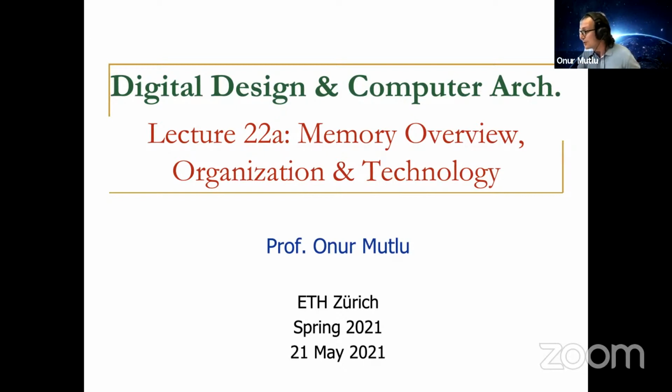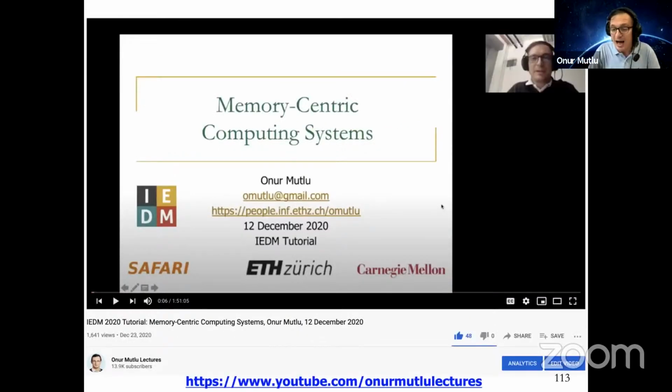So there's one more question. Is it also vulnerable to some kind of RowHammer attack? So that's another excellent question. So I believe internally, yes. But RowHammer attack is an example of a read disturbance error. Disturbance, what does that mean? Whenever you're accessing some memory cells, you're disturbing some other memory cells.